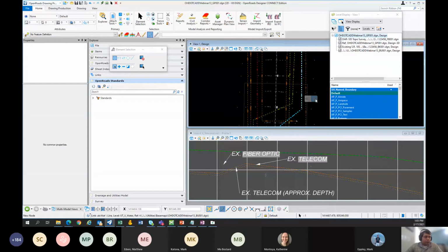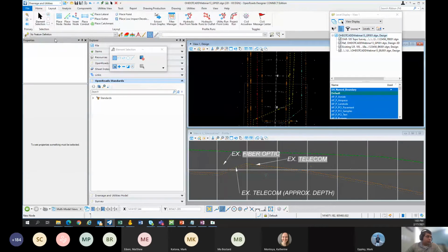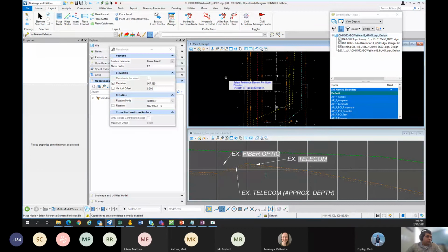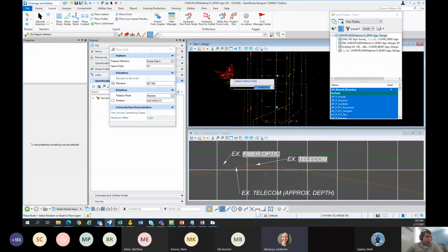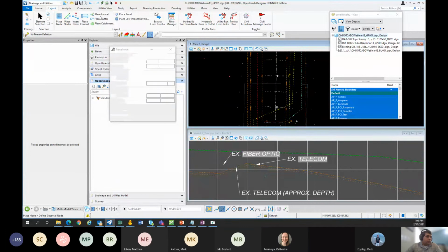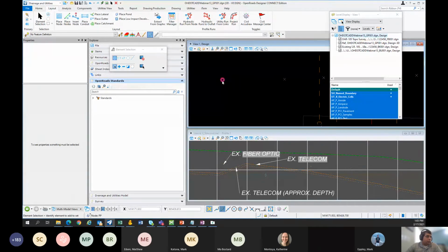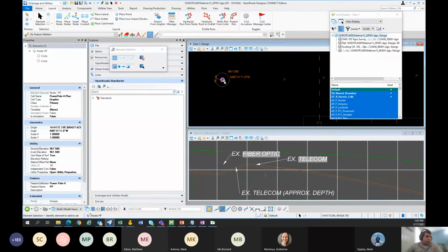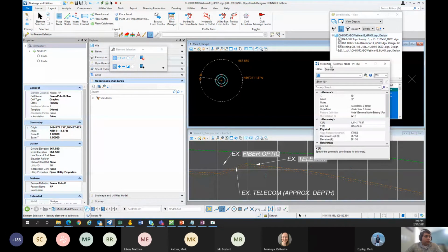I also noticed there's this bug in the latest release where it doesn't ever actually open the utilities dialog if this is across a reference. If you want a quick workaround, you have to go and place just anything, any kind of utility in this file, and then this one will let me open this dialog.